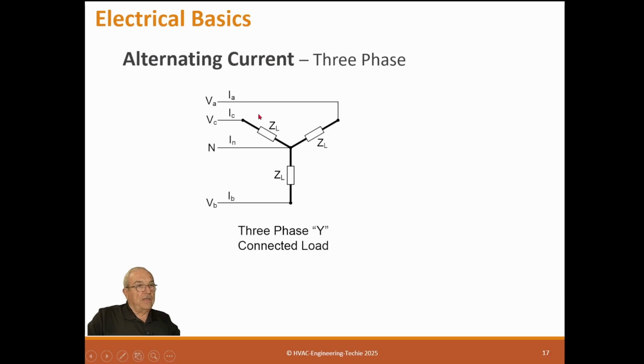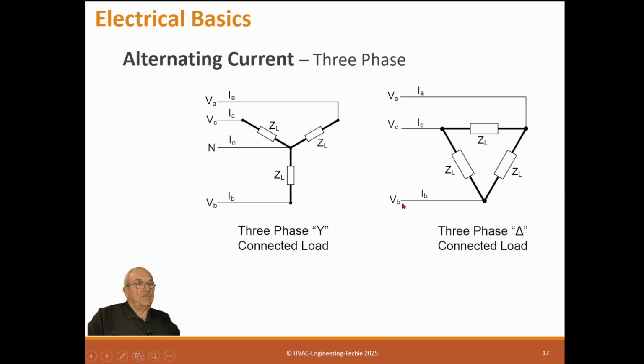Alternating current three-phase. This is a Y transformer we were talking about. See where it has A, here it is, A, going this way, A, B, and C. This is a Y transformer, and the neutral's at the center tap. This is a delta transformer. You can see it's got A, B, and C, going this way, A, B, and C, but it has no neutral. If it has a neutral, it'll be connected in the middle of one of these windings, and that's a delta load, and we'll talk about that in a minute.